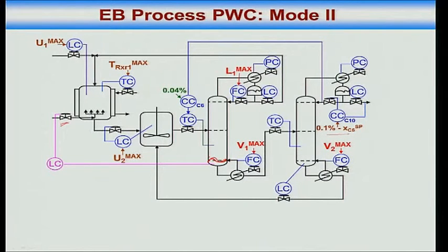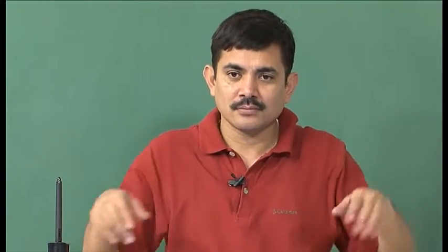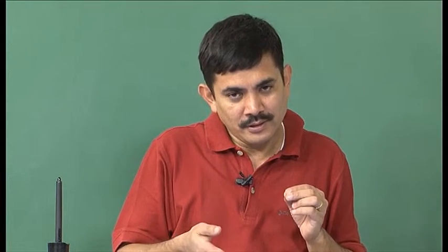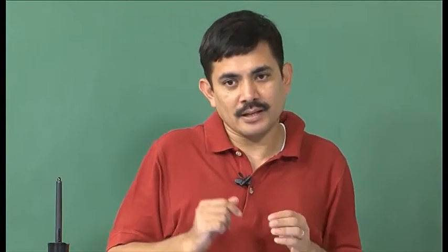Okay. Alright. So, we don't need very tight control. No, it's not a question of very tight control. You see, what happens is, even for a 1% change in throughput, there is no throughput manipulator here. Even for a very small disturbance, let us say a 1% change in one of the set points, either temperature or pressure or composition or whatever, the bottom level in the recycle column either overflows or runs dry. That means the level control is fragile.